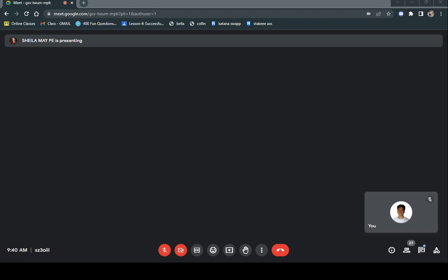Okay, so we are done with the VGS part now. Next we need to find our VD, VS, and VDS. So VD, what's the formula for our VD? VDD minus ID RD.